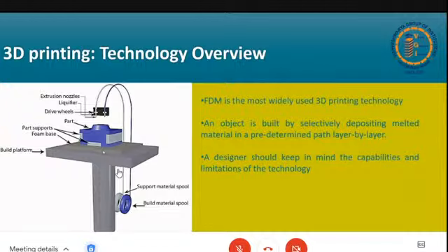But if you reduce the layer height to, let's suppose, half mm, 0.5 mm, you will have 20 layers in the same 10 mm, and the layers will be less prominent. You will be able to see less of that, the thickness will be less. And you can go up to 100 micron.